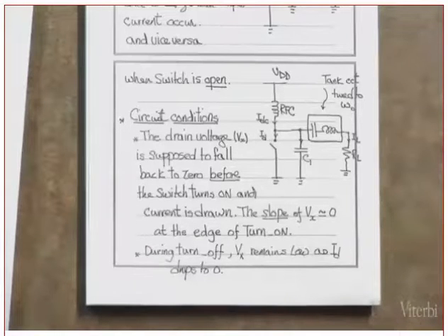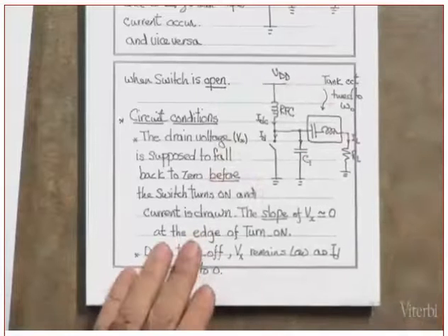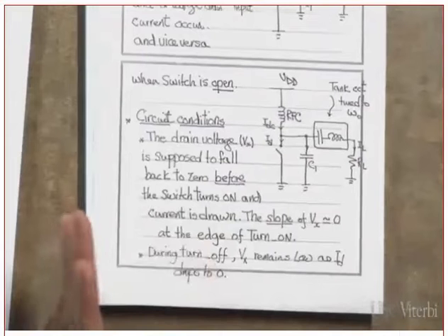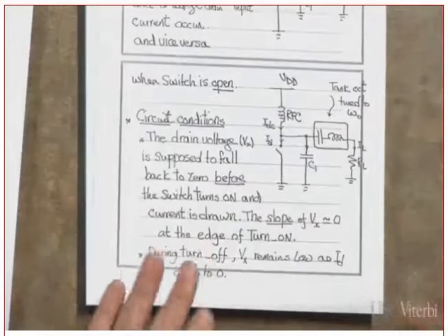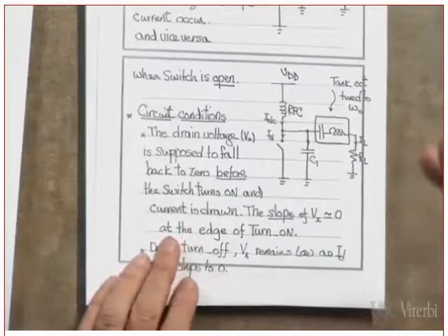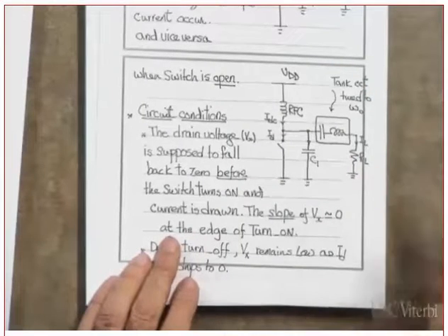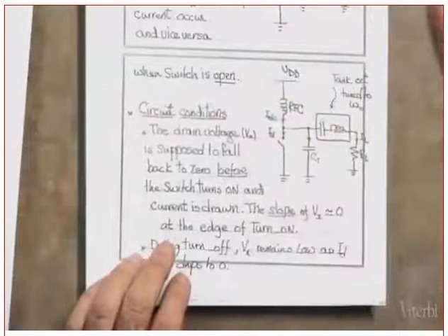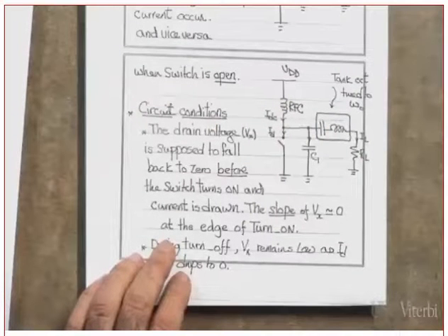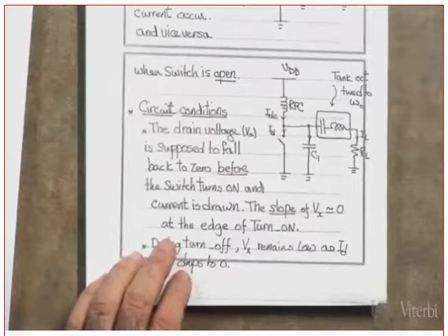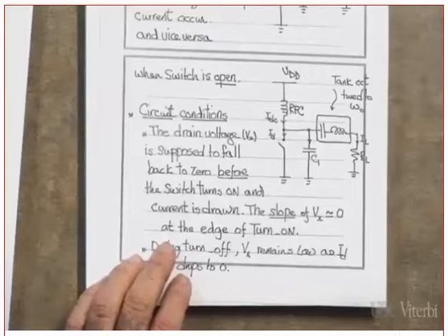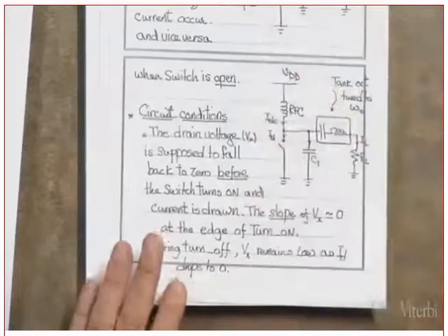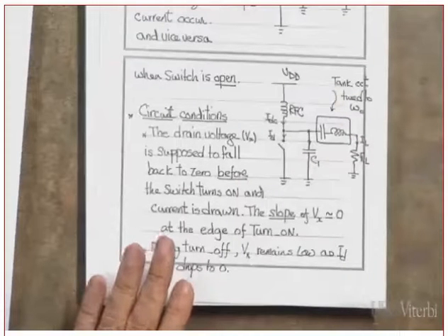What does undamped mean? When we say this circuit is undamped, what does it mean? It keeps oscillating. Undamped. When we say underdamped, what does it mean? At the beginning, I cannot believe I'm spending time on this. You should have had it before. Underdamped means you start oscillating, but the oscillation will die down with time. Clear? Okay. Overdamped means there won't be any oscillation.